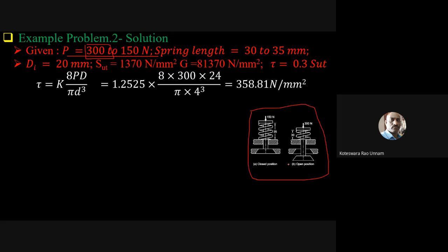Suppose I'll show you a problem also, how they can give it, if you want to use fatigue equations, how they can frame the question, or how you will get a question from an examination point of view. That we'll see while discussing those problems. For the time being, what you need to remember is, even though the load is changing from 300 to 150 newtons, you need to design for the static loading only. So that's what we did in this problem.